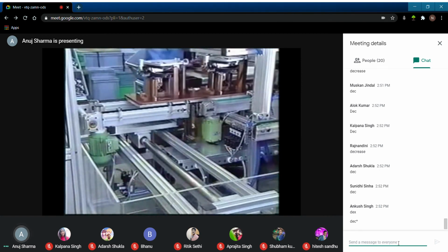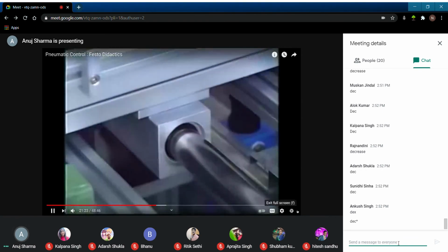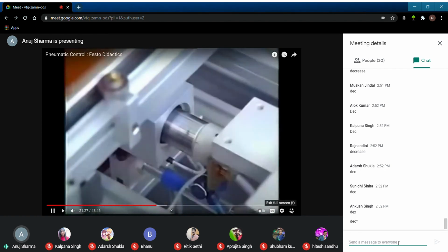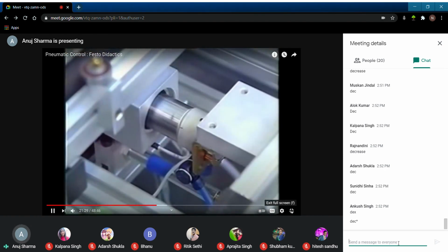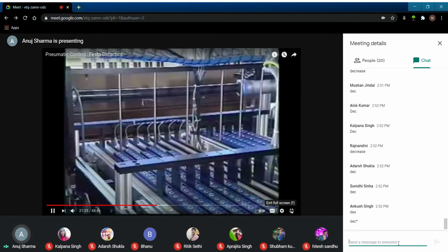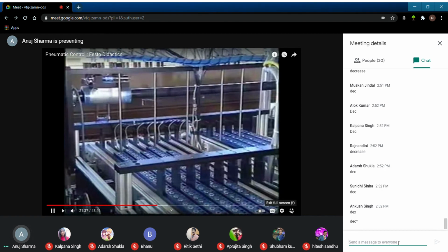Built into the piston is a ring-shaped permanent magnet. Mounted on the outside of the cylinder is a part called the yoke. It also contains a magnet. The piston and the yoke are magnetically coupled. As the piston moves, the yoke moves exactly the same distance. Rodless cylinders are ideal for long-stroke applications, effective up to 10 meters.